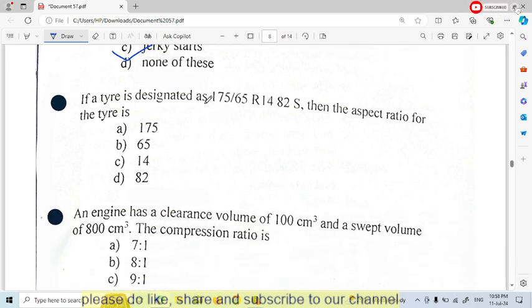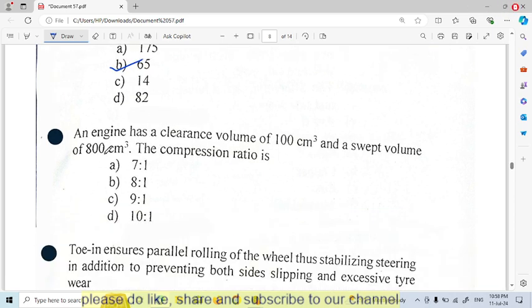If the tire is designated as 175 by 65 R 14 82S, then the aspect ratio of the tire will be 65. And an engine has clearance volume 100 cubic centimeters and swept volume 800 cubic centimeters. The compression ratio is 800 by 100, that means 8 to 1.